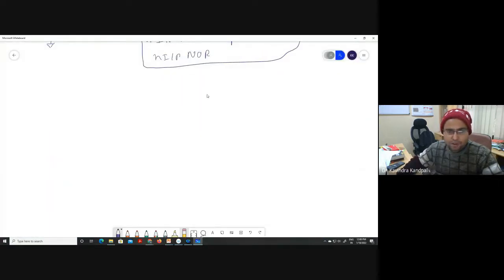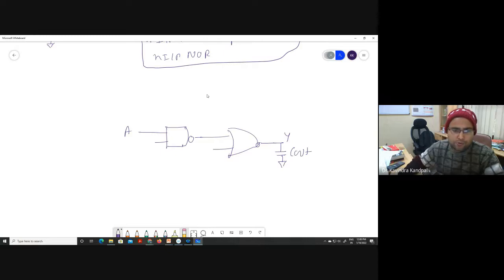Let's say one 2-input NAND gate is driving, I'm giving you the simplest example, a NOR gate. And this I can say is my C out, and I also know my input capacitance, that is C in. So what will be my path electrical effort, anyone? This is C out divided by C in. Yes or no? Will it be C out by C in? Yes, sir.